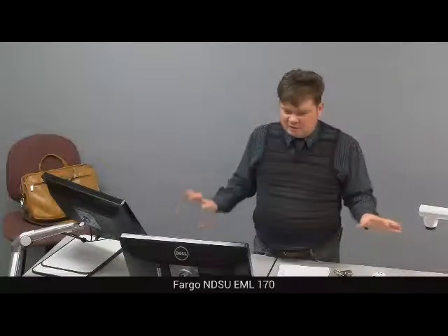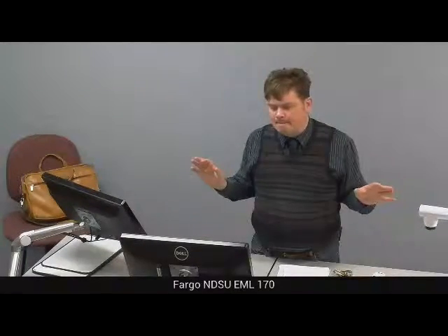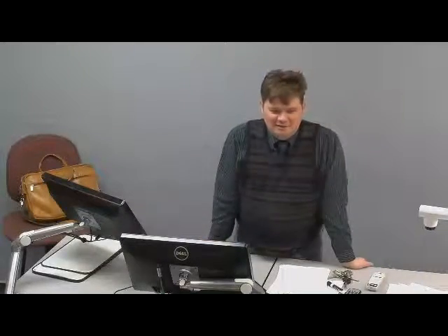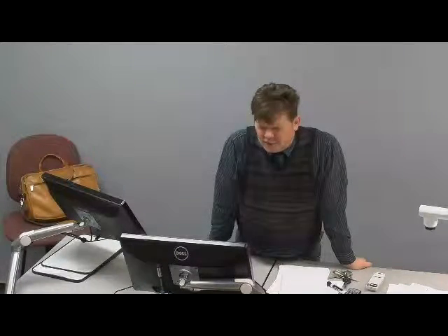Okay. But there is a thing that, stop me if I'm telling too much or something strange. I'm kind of considering it self-evident, but it could be not, so please keep me under control. I suggest not just a simple single point for anions and cations. I suggest molecular dynamics in an anion and cation environment. So you take the INCAR for molecular dynamics and you add there a keyword that modifies your number of electrons.